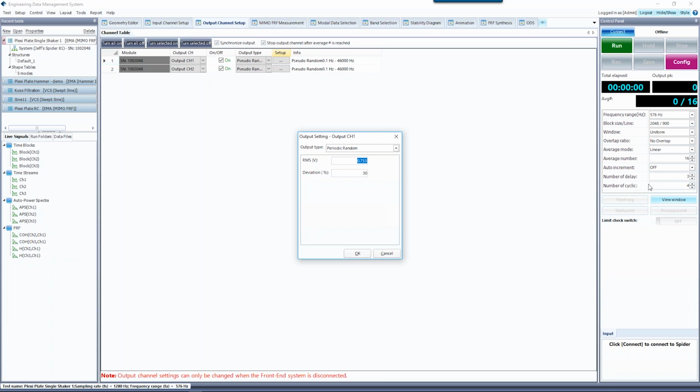For my case, I set up to 30 or 40%, and I can set up the level. So this is a constant level. But for every frequency point, when I say create a new theoretical random block, the level will also be randomized from one line to the next. So by just changing that, it's totally randomized, the amplitude and the phase for each frequency point.